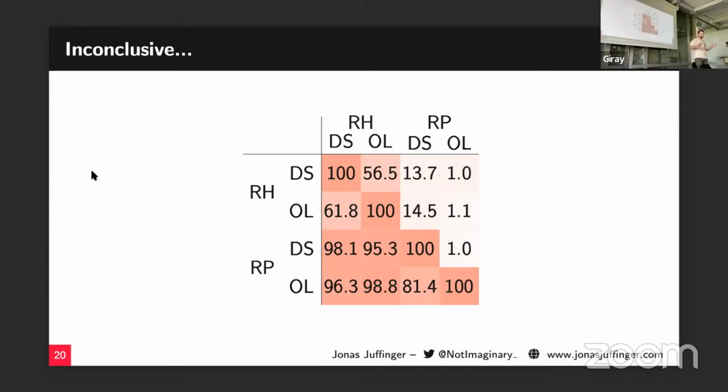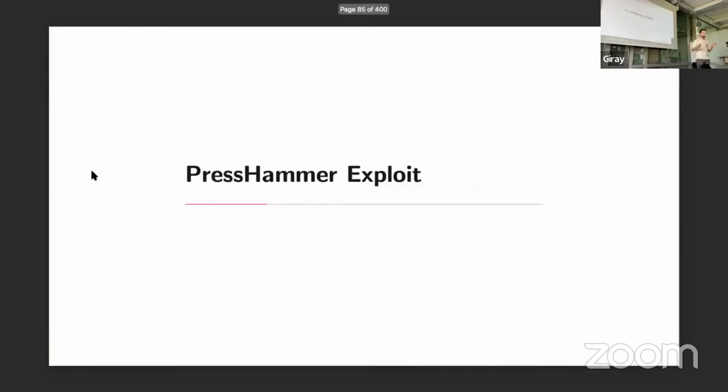Our theory is that actually one location RowHammer can induce bit flips through both effects. Because of this memory controller that has to close the row after 9 times tREFI, we still perform RowHammer. It's slower RowHammer, but we still perform RowHammer, but we also do RowPress by keeping this row open quite long. And so we think that one location RowHammer can actually cause both effects, and we see bit flips of both sets. Yeah. And then we built an exploit with that because exploiting is always fun.